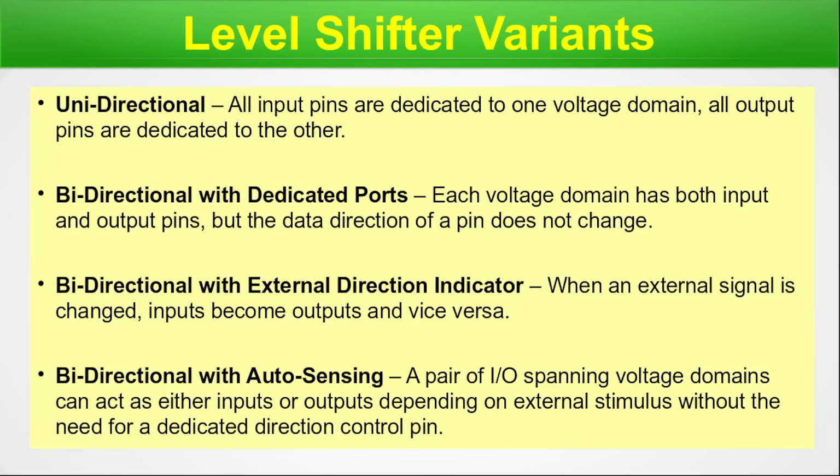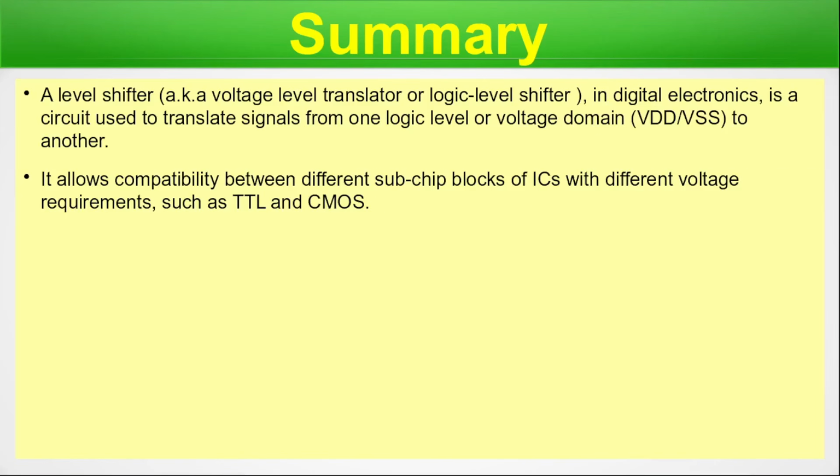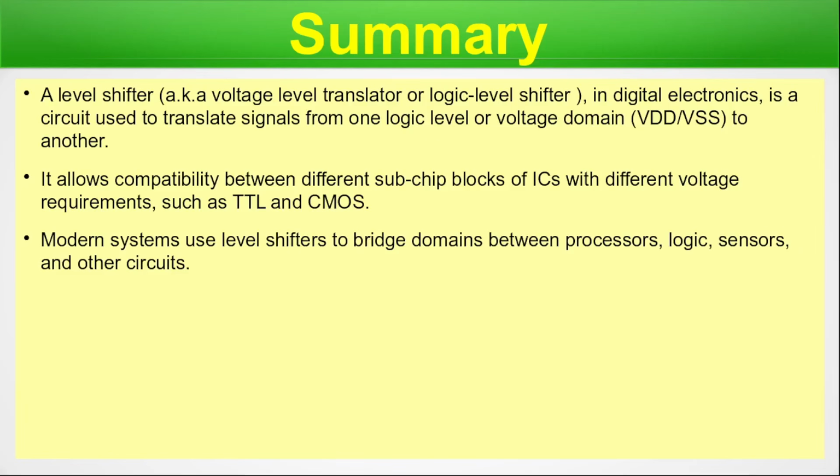We are done with this particular slide, so let's move on to the next slide. Summary. Let us summarize what we have discussed so far. A level shifter, also known as a voltage level translator or logic level shifter in digital electronics, is a circuit used to translate a signal from one logic level or voltage domain to another. It allows compatibility between different subchip blocks of ICs with different voltage requirements, such as TTL and CMOS. Modern systems use level shifters to bridge domains between processor, logic, sensors, and other circuitries.